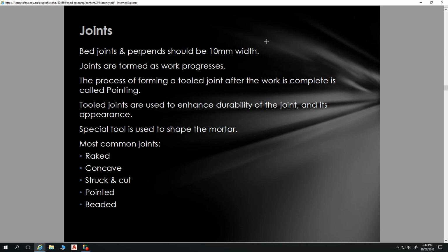But that's it. That's all that bricklayers will want to do. If for some reason your windows and doors don't work in with those brickwork dimensions very well, but are fairly close, what a bricklayer can do is stretch out their perpends. So it says here they have to be 10 millimeters in width, but they can actually stretch them out to 12 millimeters or so. So make them slightly wider and gain 2 millimeters each brick. But yeah, you won't be a very popular draftsman with a bricklayer if you're getting them to do that.